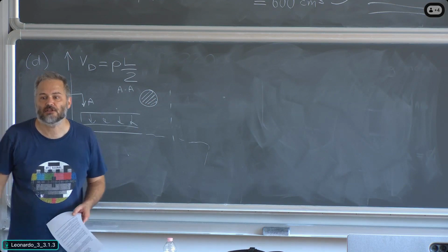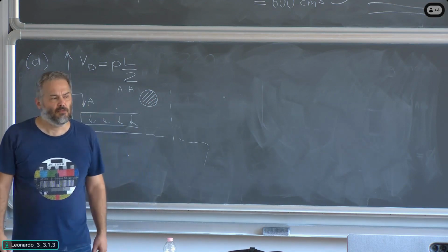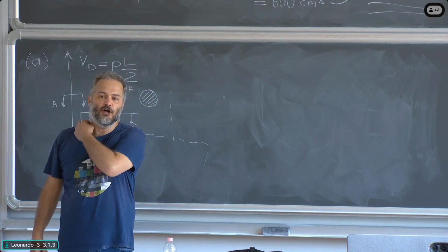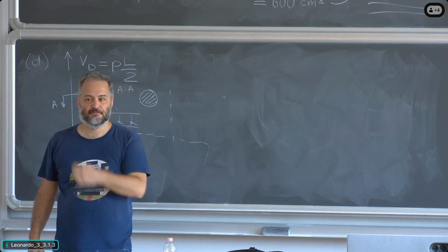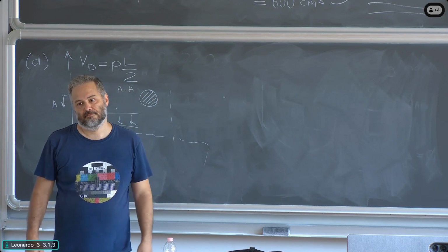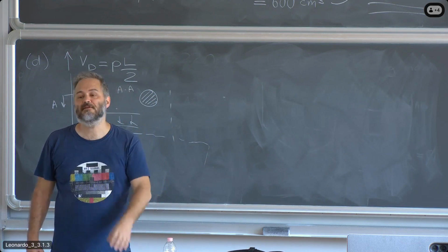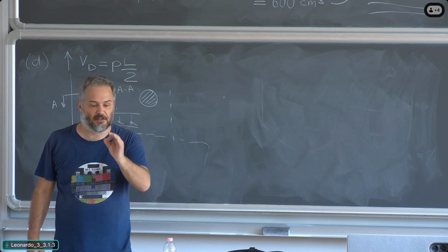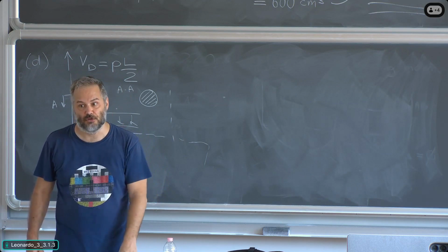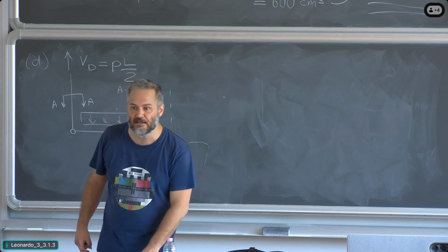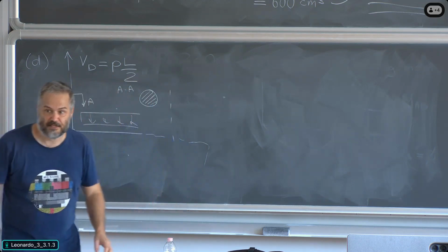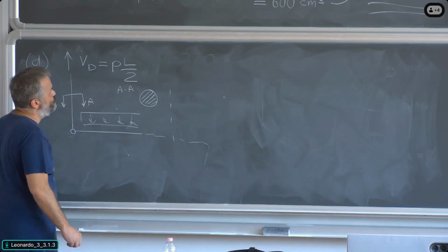Not 13, not 11. Why do we only have even diameters and not even and odd diameters? Because if you only have 1 millimeter in difference, you cannot tell the different bars one from each other because the difference is too low. You cannot see it with the naked eye, differently from the case where you have 2 millimeters. Maybe easier to understand or to distinguish it.